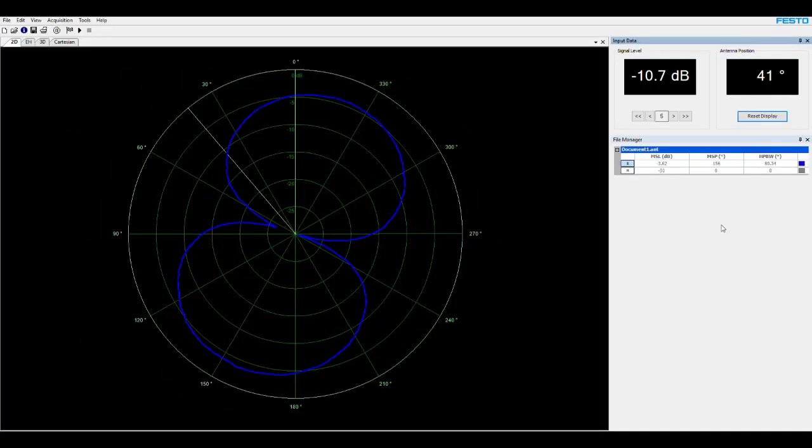So what you see on the screen is an E-plane cut co-pol that we already performed. In this case, we have a half power beamwidth of about 80 degrees using 5 dB attenuation that I applied using software. So you can also compare this measurement with the previous co-pol E-plane to understand the uncertainty associated with these measurements.